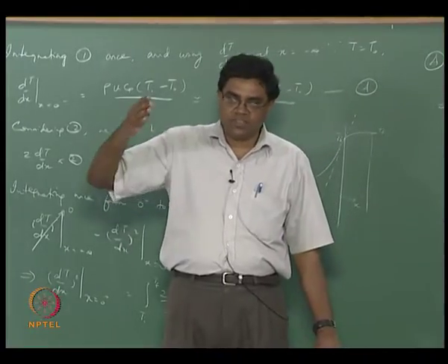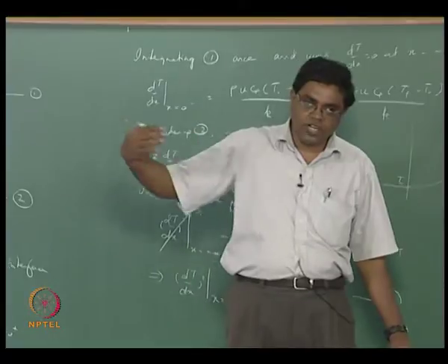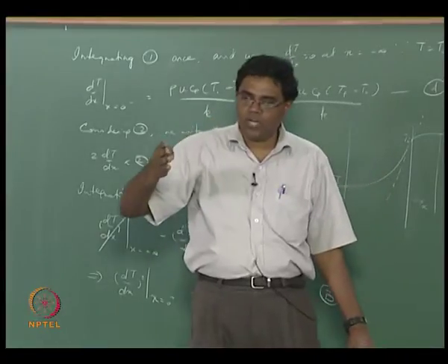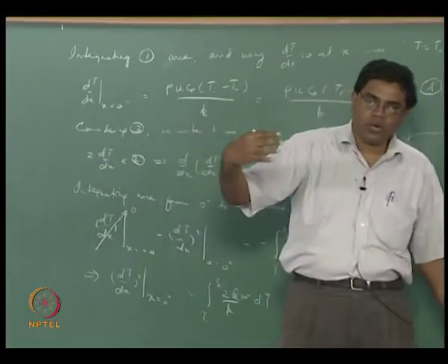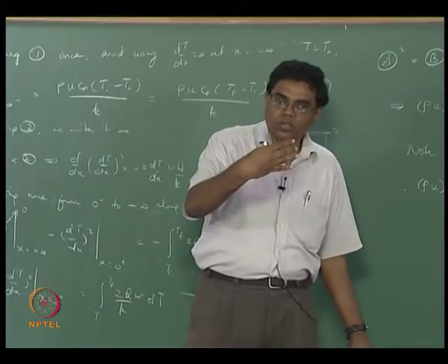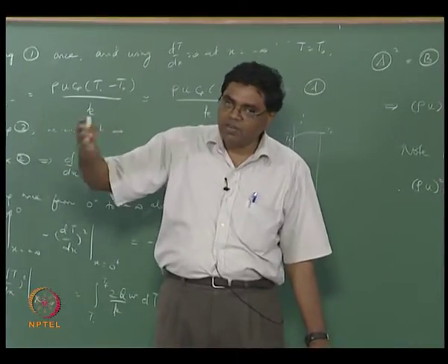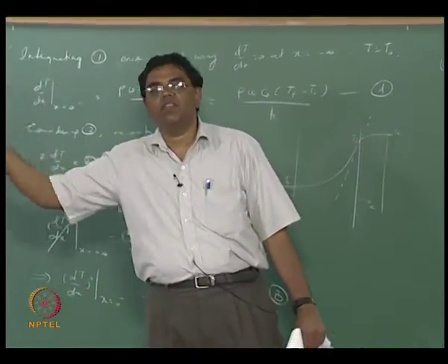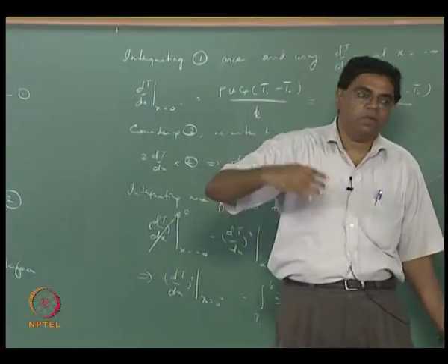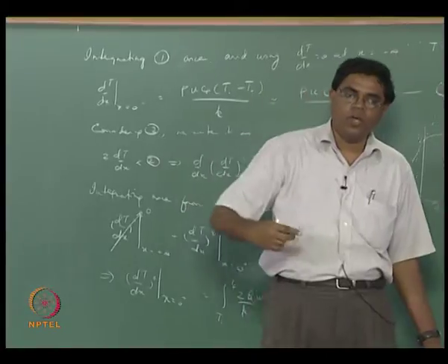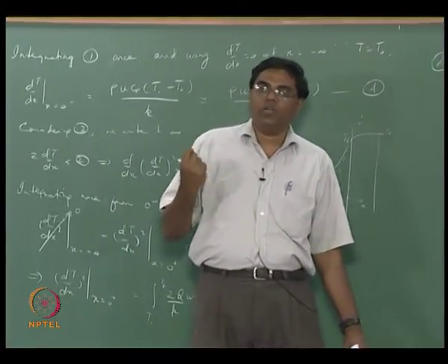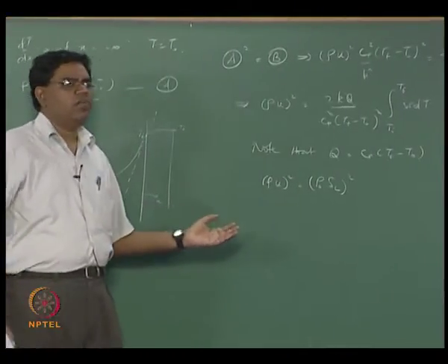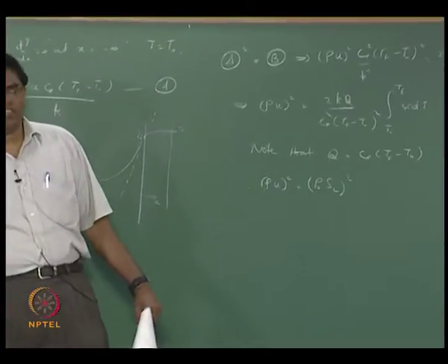you could be actually sitting on the flame and getting the reactants to come into you at the same speed, or the other thing that you can think about is you now have the flame that is propagating, and then the products are actually flowing out, you see. Now if you are actually looking at the flame speed relative to the products, you will get a different speed when compared to if you are looking at the flame speed with respect to the reactants, because the reactants and the products are having different speeds themselves. Therefore it's always quite important for us to note what the flame speed we are talking about, and usually we are talking about a flame speed with respect to unburnt still reactants.